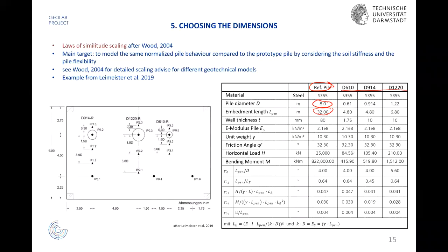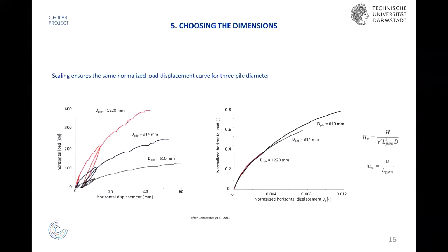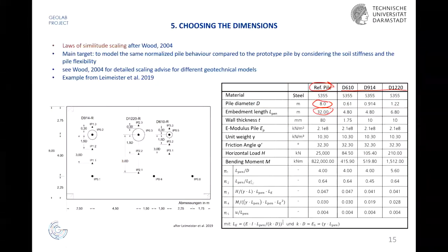So let's look here at these piles. We have the dimensionless. So okay, how can I explain that? If you purely look at the diameter, or on the force, this is not always representative. You should look on the ratio, for example, of your penetration depths to your diameter, or of your penetration depths to your elastic length of the pile.